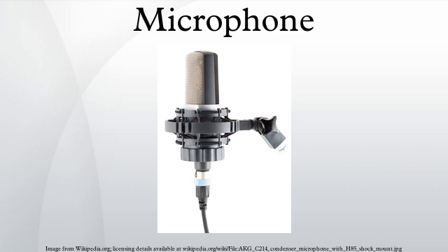The self-noise or equivalent noise level is the sound level that creates the same output voltage as the microphone does in the absence of sound. This represents the lowest point of the microphone's dynamic range, and is particularly important should you wish to record sounds that are quiet. The measure is often stated in decibels A, which is the equivalent loudness of the noise on a decibel scale, frequency weighted for how the ear hears, for example, 15 dB SPL. The lower the number the better.